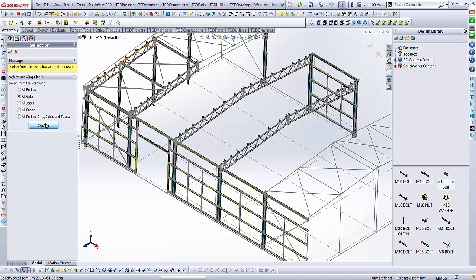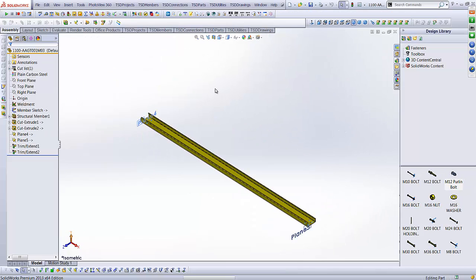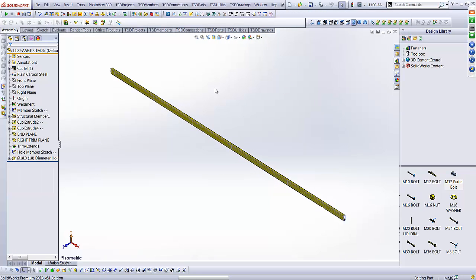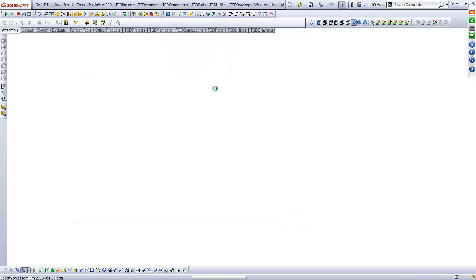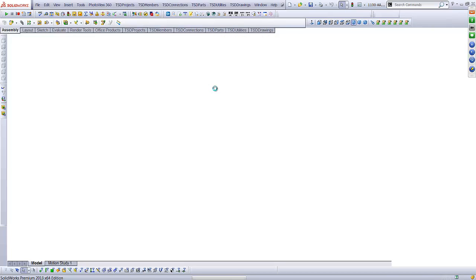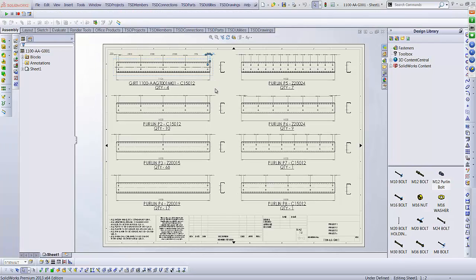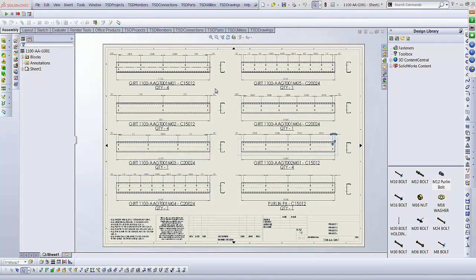So we just click create. Now at your end you may not see the processes happening, but what it's doing is going through every girt in the job, every fascia that was there and in the processes. Now you might get a white screen, which I apologise for, because of the battery, and it's counting the holes, getting the section size, and now it's opening up drawings. Now it's updating dimensions, populating the size, the mark number, and punching. So you're pretty much right to go.